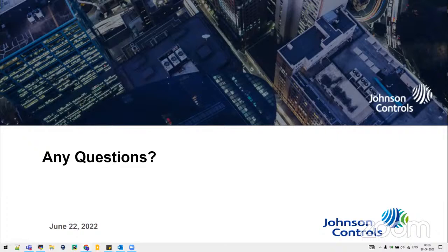Yeah, this Mask RCNN model, we are running at 10 frames per minute. The real-time requirement for this project is very low, because as I discussed, the flow meter reading comes out per hour. It gives only 1 reading in one hour. So for this one, we ran it at low FPS. And the second thing is the machine on which we ran is a non-AVX machine. It's, I think, a 10-year-old system, which is very sluggish, and they are running only one solution on it. We didn't want to burden it with much more than is required. If given its full potential, the solution could run at 5 FPS also.